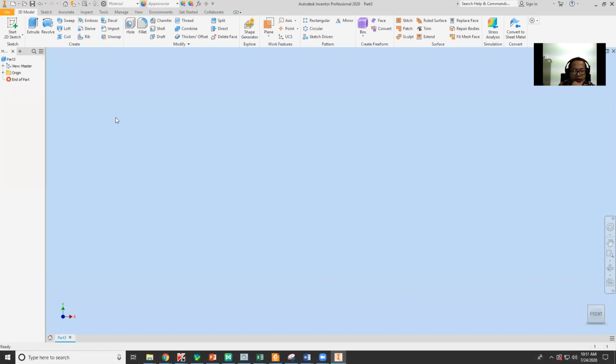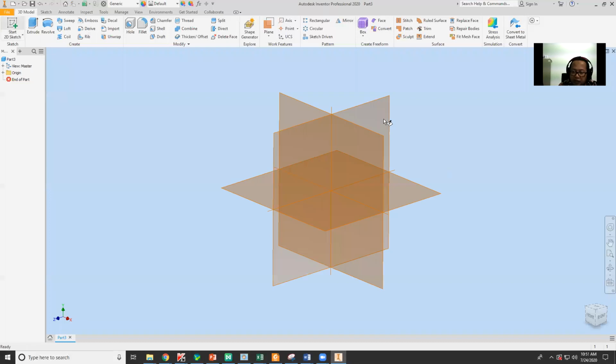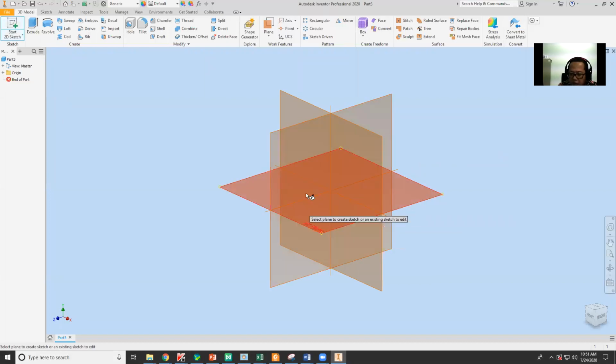Before, we already learned about 2D sketch. This is the tool for 3D process editing. Now please follow me. Just click to the sketch, and we can select whichever plane. For the early beginning of design, I suggest you just use this XZ plane, because it will extrude from the bottom to top, right? Then we click this.